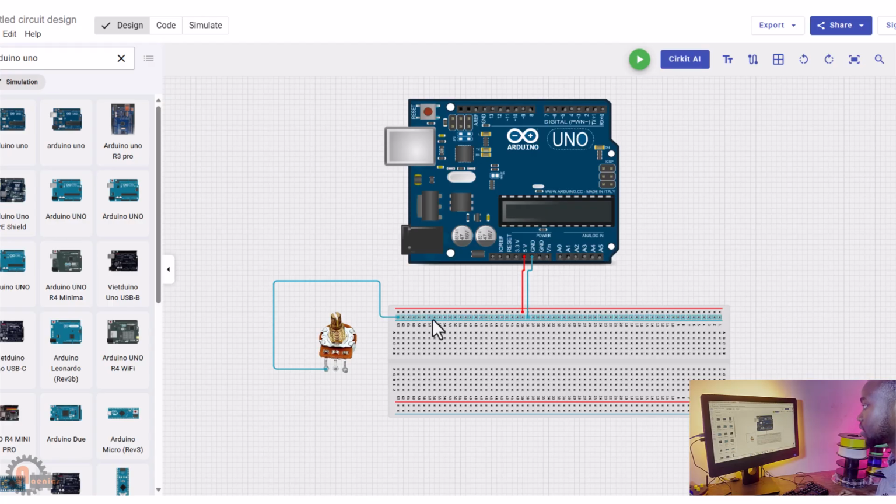I've connected it to this lower part of the circuit, and then it is in turn connected to the ground of the potentiometer. So the next thing I must do is to connect the VCC also to the same power line, which has already come from the Arduino, 5 volts, right? Good. So I've just powered the potentiometer with 5 volts and ground.